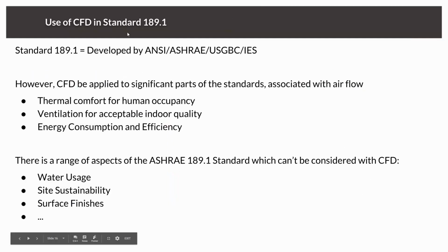And now let's talk about how we can use CFD for green building. As you know, when it comes to green building, a very important point is certification and sticking to standards. Let's start with the bad news. Unfortunately, in the past, when most of the standards were developed for the first time, simulation was not an industrially relevant tool. But there are some standards already where you can apply CFD, including the ASHRAE standard 55 for thermal comfort and the ASHRAE standard 62.1 for ventilation.